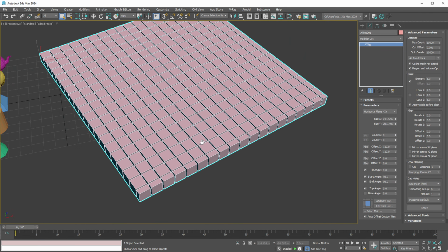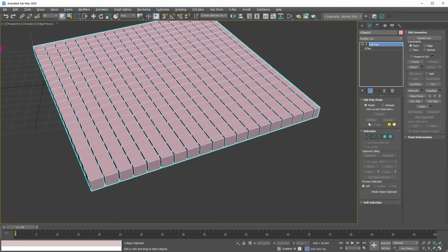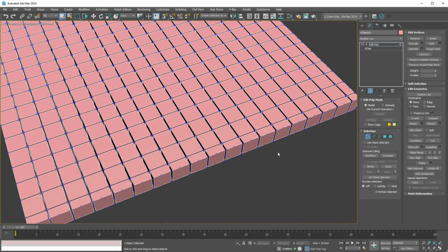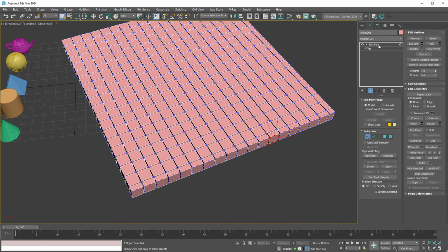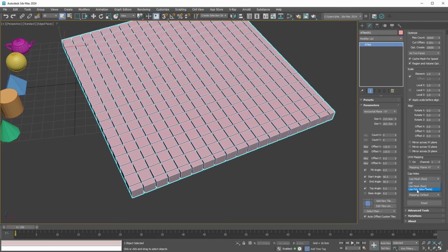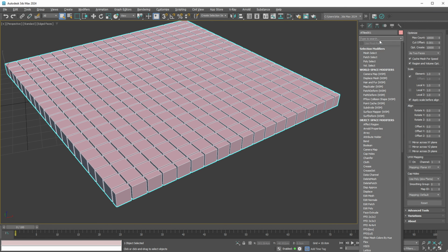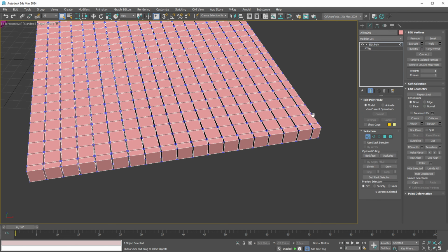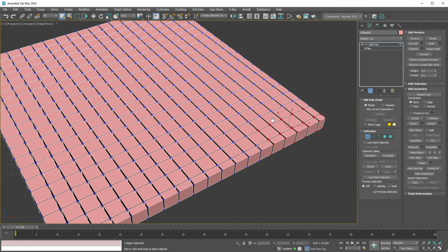The Use Mesh option is selected for fast interaction, but the resulting objects may not have the optimal topology. This method adds additional vertices along the edges, which may not be ideal for further editing. For this reason, we've introduced another option, Use Poly. This option is slower and is still in beta, so it may pose occasional compatibility issues with 3ds Max. We recommend using it only when absolutely necessary. When selected, you'll notice that the update process is slower, but the generated mesh is clean without the extra vertices produced by the first method.